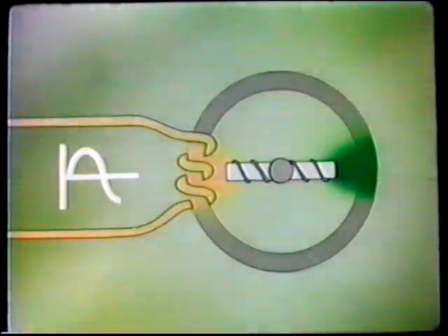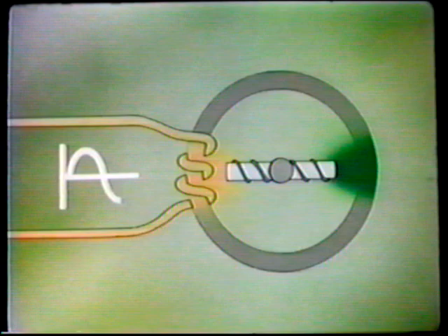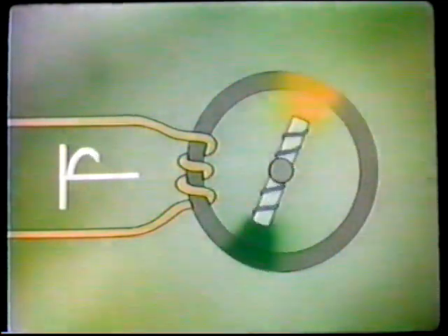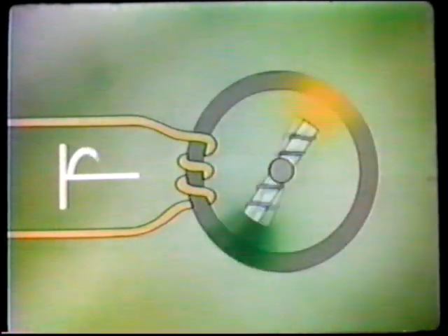During the next quarter turn, the rotor's south pole sweeps across the coil. Maximum voltage is induced in the coil. But now its polarity is reversed because the coil's under the influence of a south pole. As we turn the rotor, the cycle repeats. The result? An alternating output voltage from the generator. We're now producing single-phase AC. You'll probably recognize that the graph of the voltage being produced by our simplified generator represents an AC sine wave.